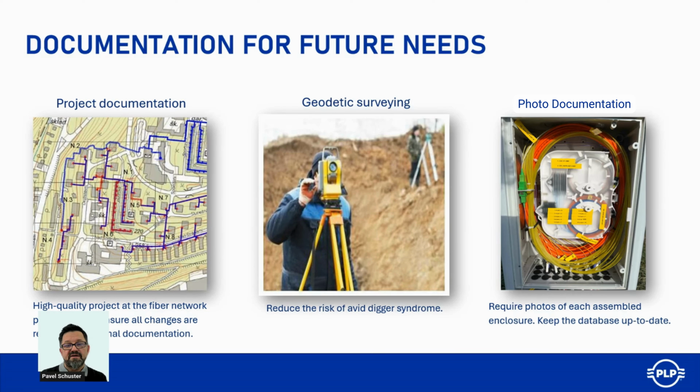Last thing, during the installation, make a photo documentation. The main reason is, first of all, in case of complaint or reclamation, you have a documentation, then it's done. And second, imagine that after 2 years, there is a group of installers which will go inside this box or cabinet and do some adjustments or reinstallation.